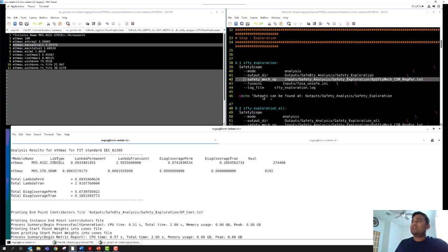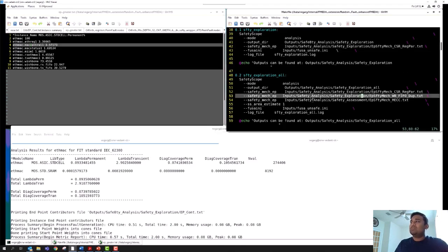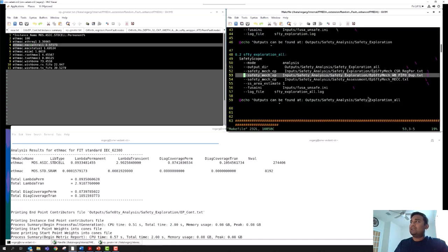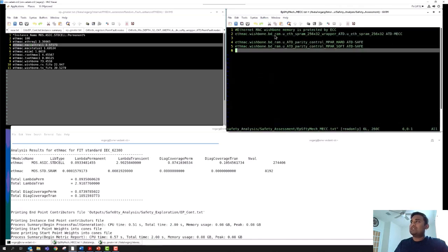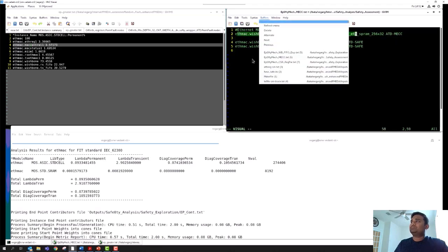And similarly, if I want to explore with other blocks which were heavy contributors, here I can set up all those experiments at the same time. So in my next run, you can see that I have set it up on the Wishbone FIFOs. I have protected both the TX FIFO and RX FIFO with duplication, and I've also added some protection to the SRAM module, the BRAM module, by some memory ECC.